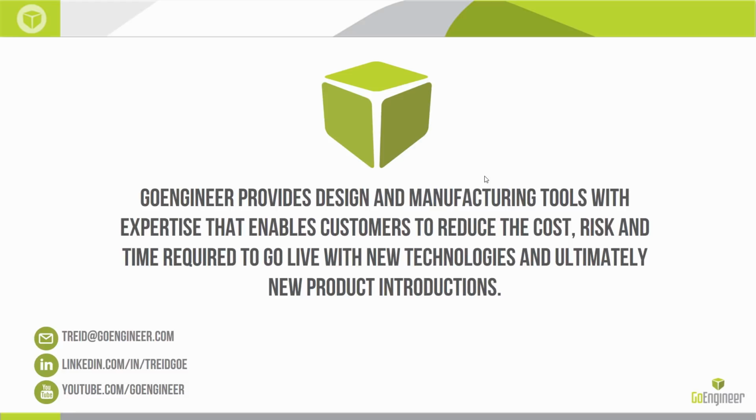Very quick overview, but it should give you an idea of what goes into creating these, going through your connections, setting up your forces, running a motion analysis. Once you have the motion analysis, probing your results to find your max force needed for your motor or your net max force for your actuator, so that maybe you can spec out those components. But then you take the motion analysis results and feed them into the shape optimization and start making design decisions based on those results. All of that together means you're going to start out with a better product. Overall, your design cycle is going to be faster, it's going to be smarter, and a better result overall.